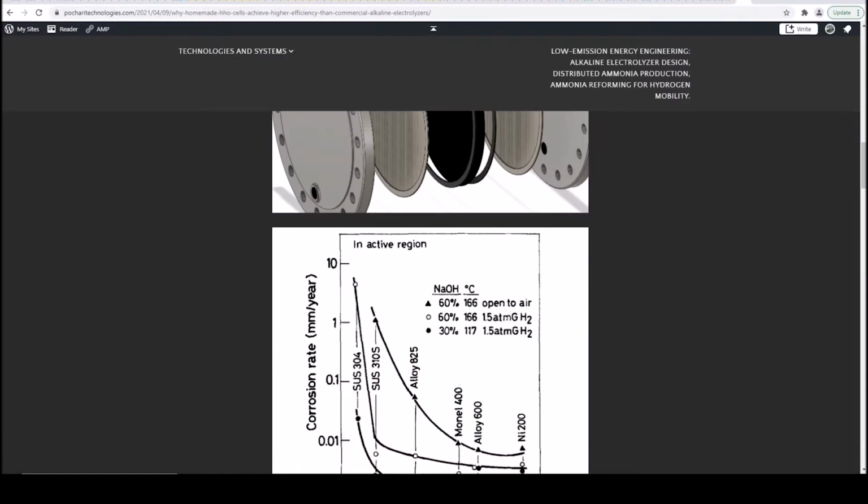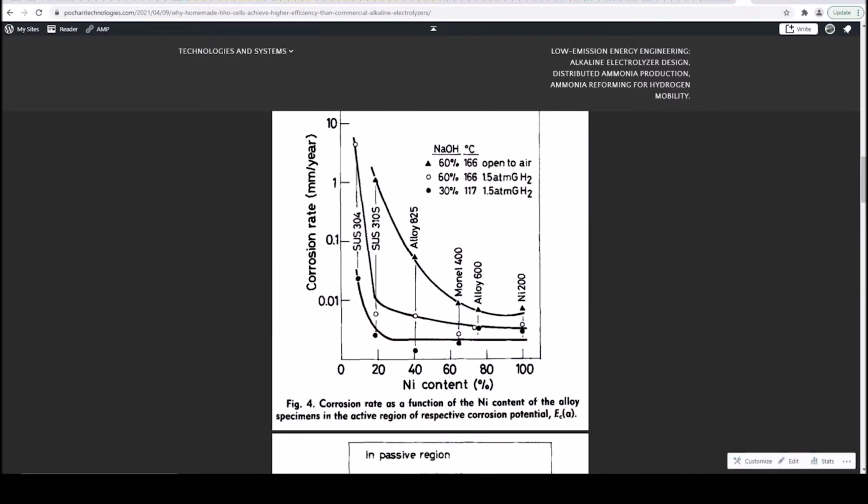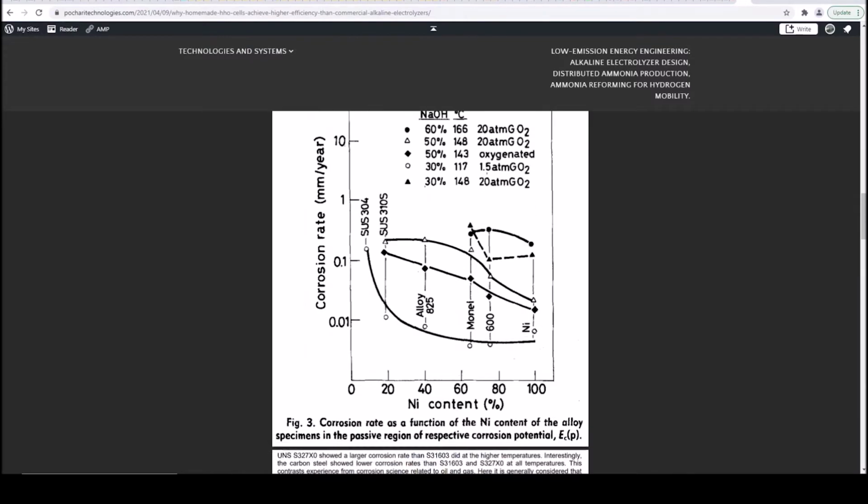So going down to the most important number you can look at, the overall corrosion rate of the electrode, because that's going to determine the loading of the electrode. Assuming 1 square meter as a metric, you could have anywhere from 100 grams per square meter used to 400 grams. It all depends on the corrosion rate.